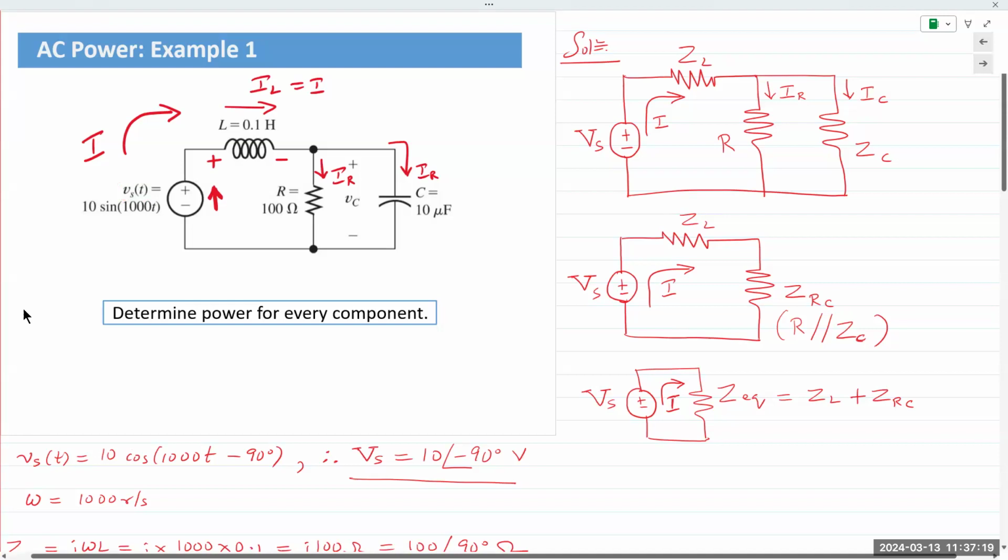So if you're in the exam, if you encounter a problem like this, and the voltage is given as a function of time, and I ask you to find the voltage or current in any part of the circuit, it is asking for AC steady state analysis. As I was saying, we are given the voltage Vs of t, we are given the values of the components. We will represent every single quantity with its equivalent impedance, and also represent the voltage source as a phasor, and then we would solve the problem.